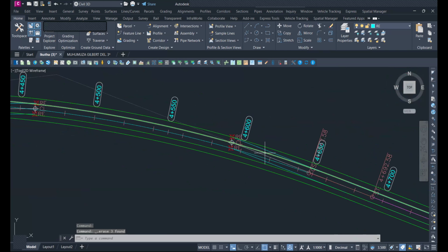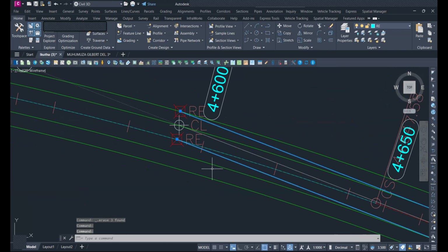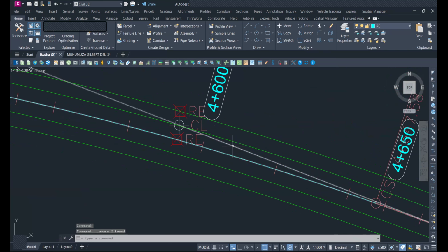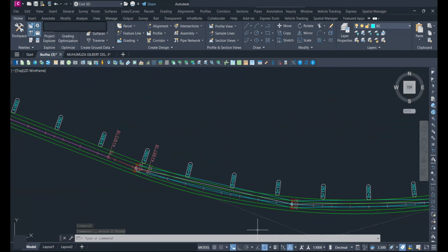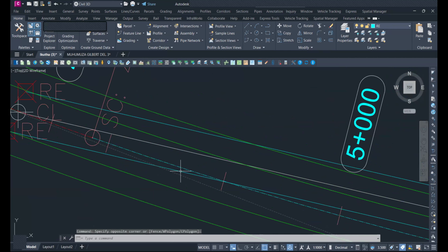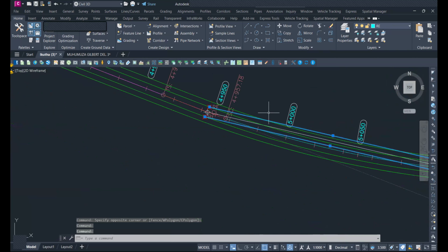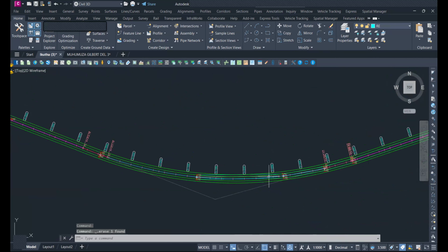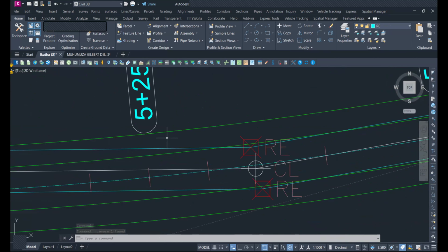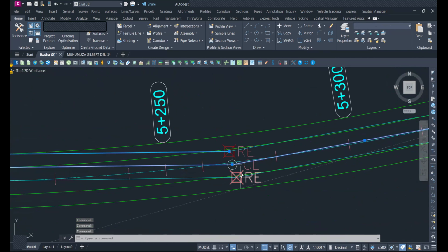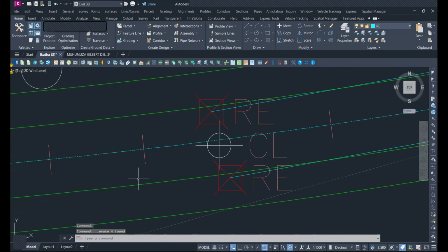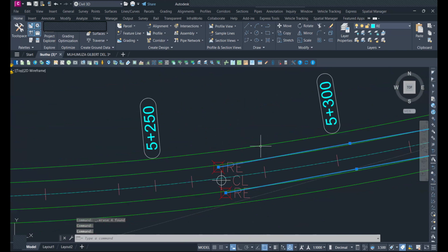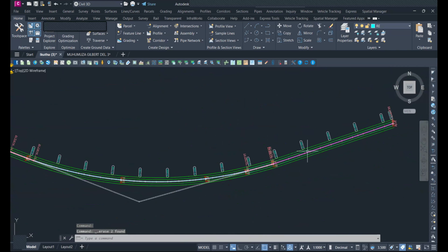roads in these areas. One thing that I'm very sure they change is in the pavement design, because of course in that case they are for industrial use, so they are not going to use the usual pavement design manual that we use in the usual road, because the kind of trucks that are going to be using your road are very heavy. They are loaded. They are very, very, very loaded. So in such a case, you cannot just use the usual design manual. So please just ask around with your colleagues or check what your local jurisdiction has.